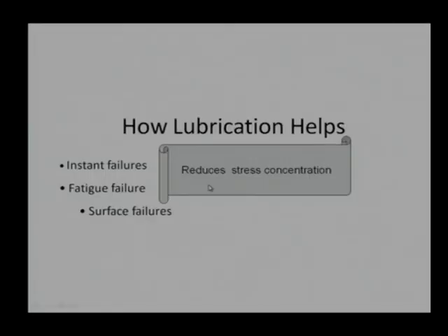In addition to that, if there is proper lubrication, it reduces the stress concentration. If there is an irregular surface, it will be filled with the lubricant, and that will reduce unevenness and stress concentration. Many times we know that the stress concentration factor goes up to 1.7, 1.8. That means if we provide a lubrication mechanism, we are going to get a benefit of around 40 to 50% on that.